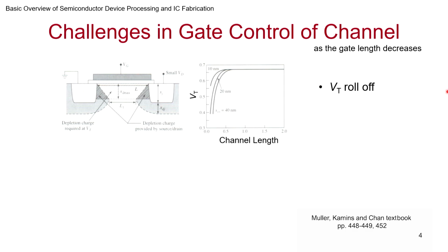But with time, that may not be enough. So you try to find other tricks to make sure that the gate bias you're applying ends up controlling the region of silicon in the channel, in the body of the transistor, and that the drain and the source have very little effect, especially the source.